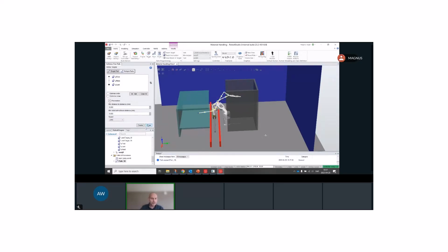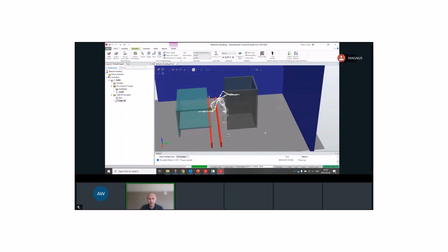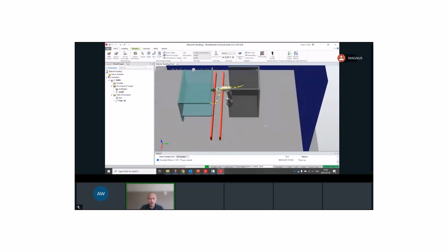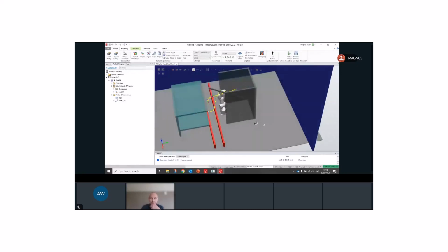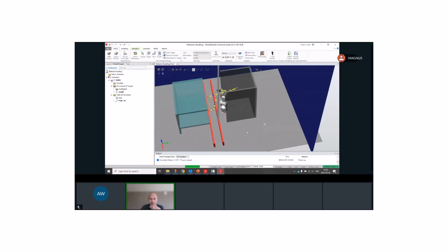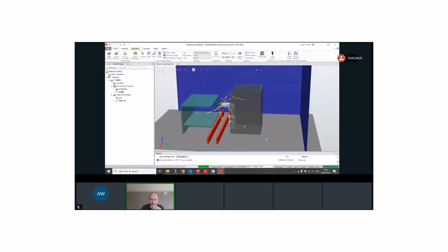And let me just run it to give you an idea. And we create a bunch of joint targets and absolute joint moves. So I just move along the path like this. And you can see the robot pulls up the rod and has this clearance and moves into the cage, swings around the rod, and then pulls it out again and bends it and twists it into this cage.